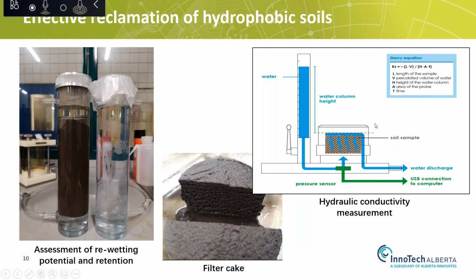So we have dealt now with several hydrophobic soils and folks looking to place those in situ, wondering if they will take on water from the environment or if they will cause groundwater mounding and have geotechnical issues. So we've tied in a few different tests, and I'll get into this one and then another in a moment, really looking at setting up experiments at bench scale in this case to determine whether these soils will take on water and how much they will release if they do. So that's some of the work that we did there.